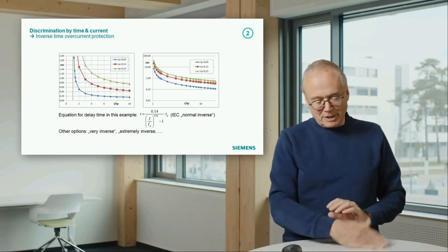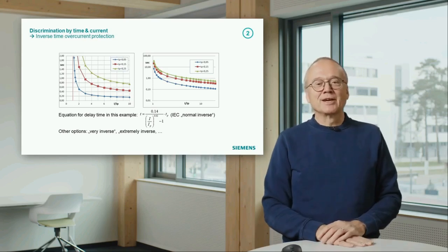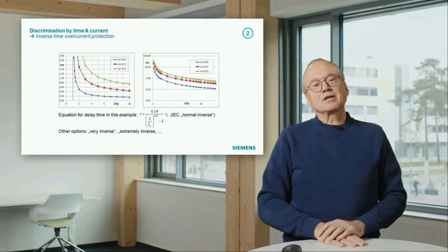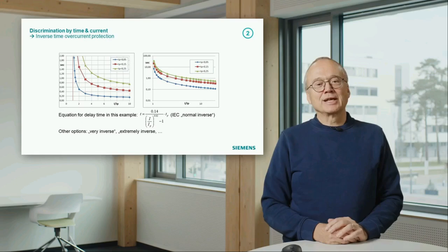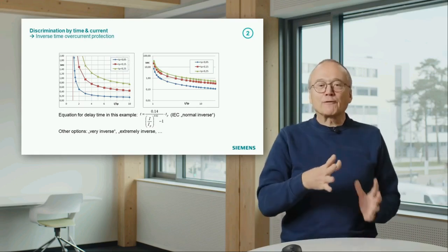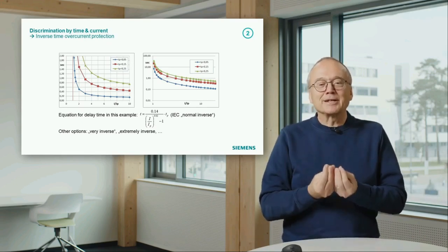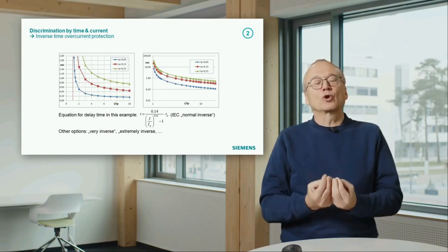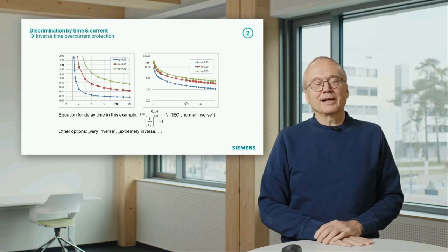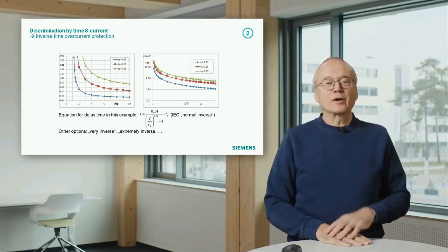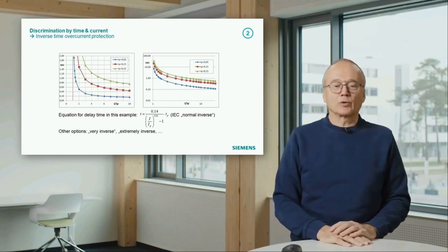That means what people in this committee did is they measured the curves from the electromechanical relays which were in operation, and then they did a curve fitting. That means they defined equations which lead to a curve which are pretty much similar to these electromechanical curves, and that is why we end up in such strange equations.